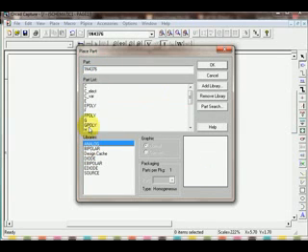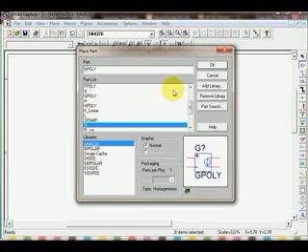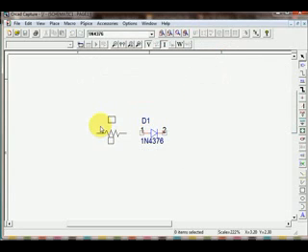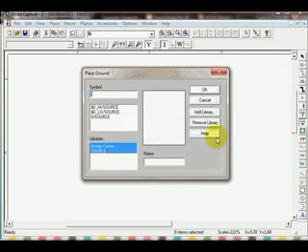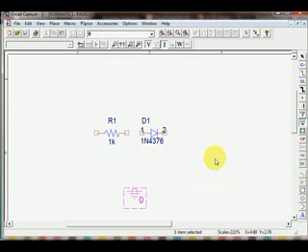I'll go to analog and type R and choose a resistor. By default value is 1k. I place it like this. Then I need one ground. Of course, without ground your simulation won't work, so if I want to simulate I have to have a ground.